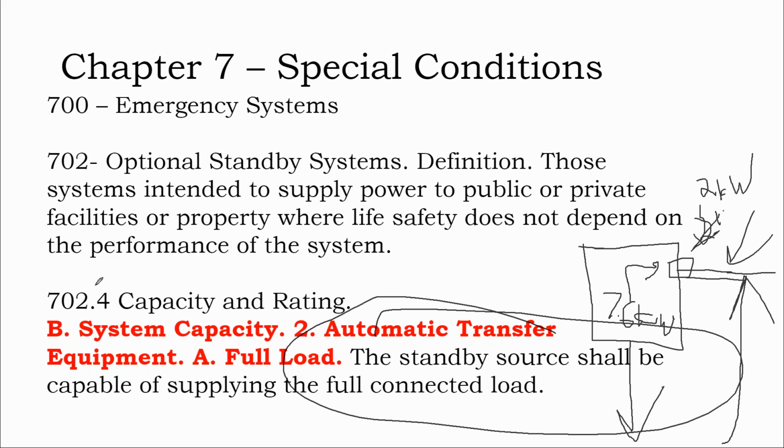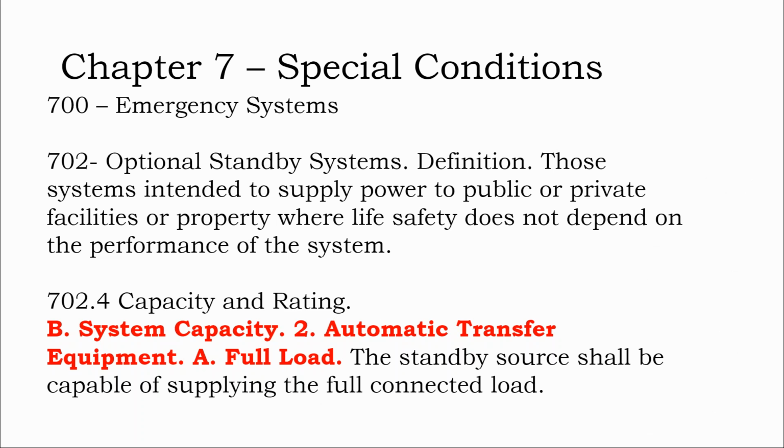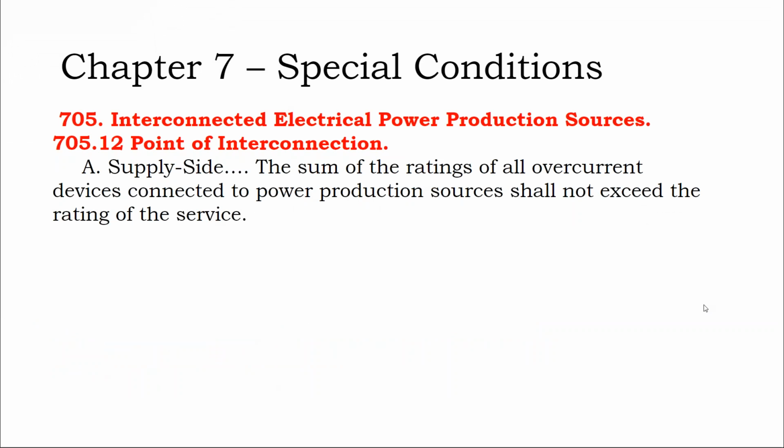So that does leave a little bit of gray area for interpretation in terms of, well, what if you actively manage your devices to put them into an emergency mode setting? But a rigid inspector could say, no, if your battery solar system is not rated to supply a 200 amp service, we want you to use a critical load panel.